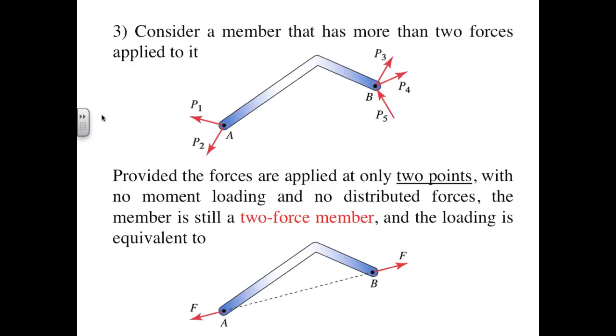In our problems, we might be looking at 5 or 6 bodies interacting in a piece of earth-moving equipment. If we had to write equilibrium equations for each of those 6 two-dimensional bodies, we would have a total of 18 equations. It doesn't take long to realize that analyzing even a simple assembly becomes unwieldy if we have to account for all that. If we can begin such an analysis by identifying all the two-force members in the system, then we can greatly reduce the complexity of the problem.